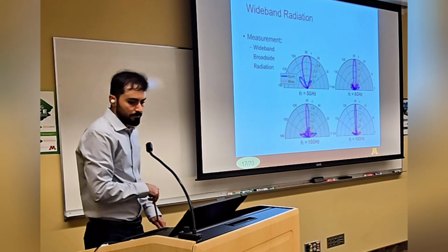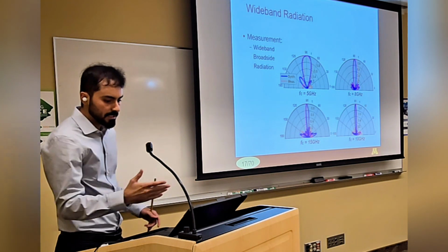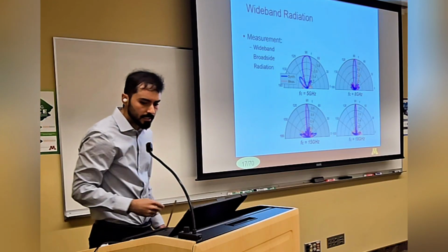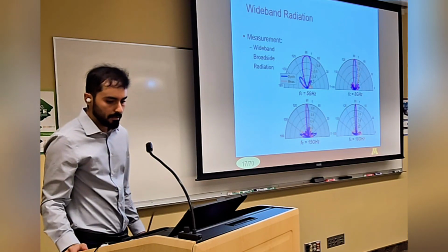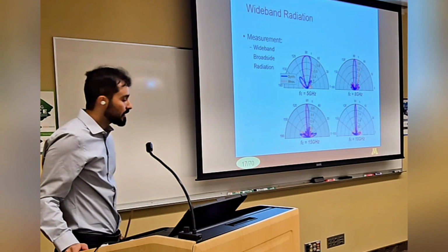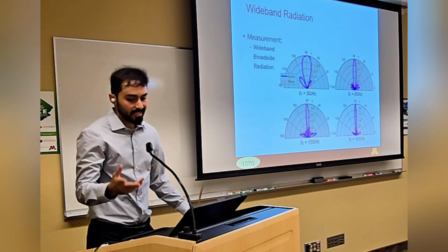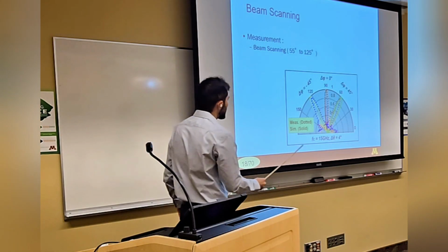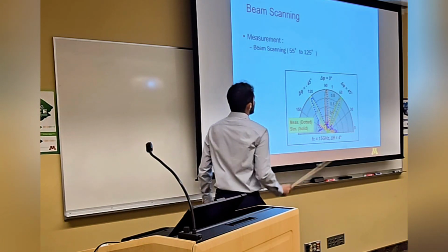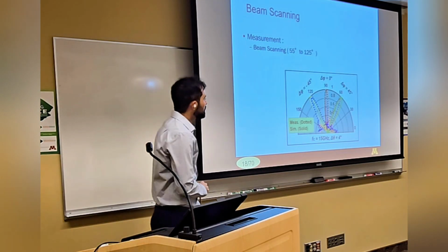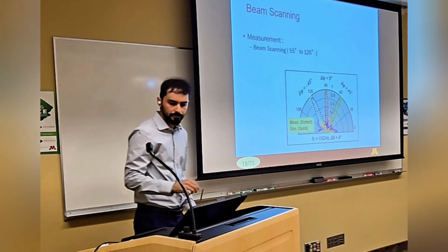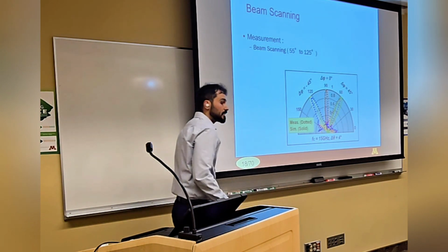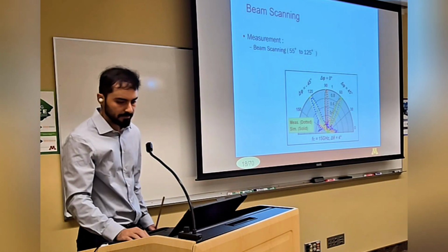This figure shows a comparison between the simulated and measured broadside radiation pattern for 4 different frequencies from 5 to 18 gigahertz. This demonstrates the ability of the multiport wire antenna to synthesize radiation patterns across a wide frequency bandwidth, in contrast to a typical phased array. And this figure demonstrates the ability of continuous beam scanning from backward to forward through broadside radiation with less than 1 dB gain variation. This is achieved at 15 gigahertz, which is also achievable across the whole frequency bandwidth.